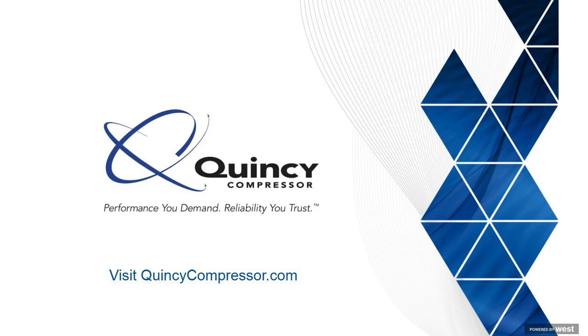But you need to ask, does that ISO 1217 data, unless it's raw data, have manufacturing variability? The answer is likely yes. What makes the DOE unique is that they require very specific accuracy of the instrumentation over a specific sample time frame, and they require you to publish the average of raw data, no statistical adjustment.